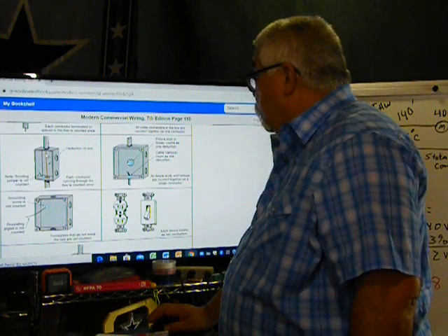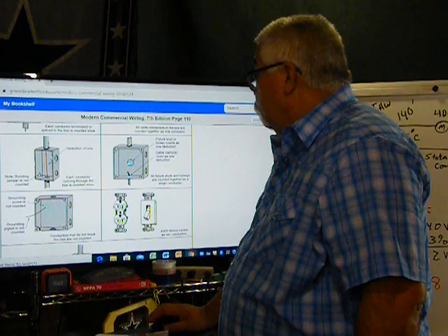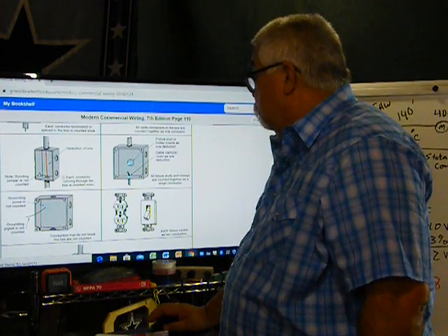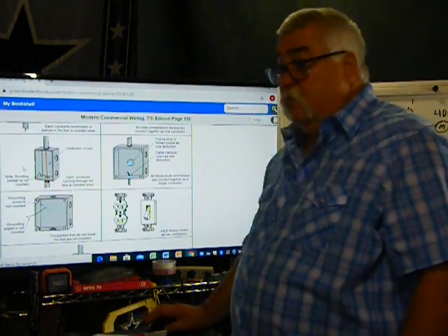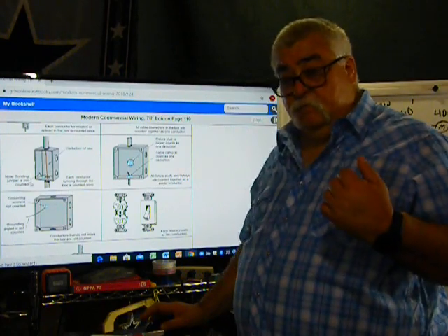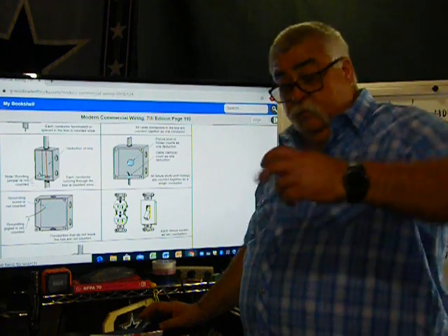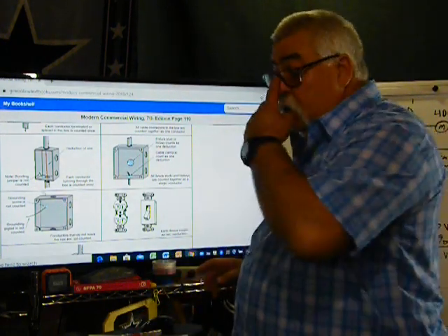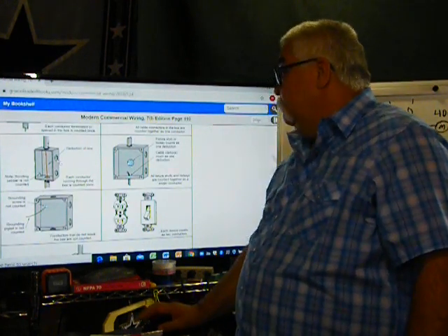If a wire comes in and goes out, there's no room or anything, that counts as 1. Okay. If it comes in and a loop is left, counts as 2. So if you leave a loop so you can make connections down the line, that would count as 2. If it goes straight through, it only counts as 1.